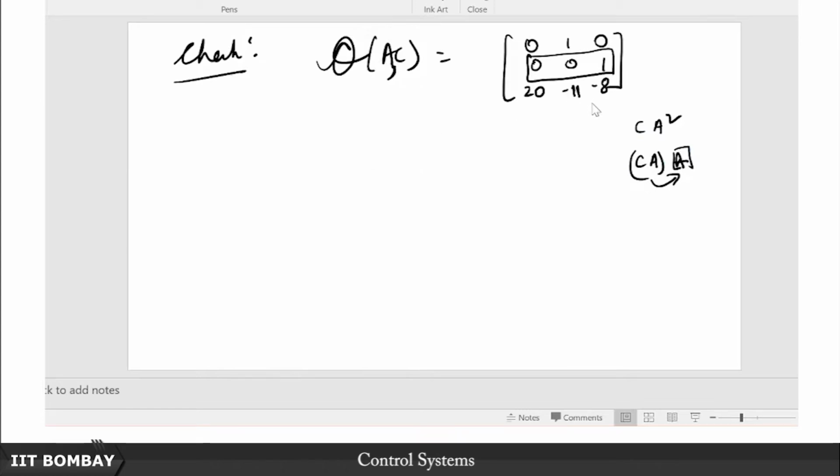This is just incidental, okay, that is what I am trying to say. So in general, do not be misled into the false assumption that the observability matrix obtained from the phase variable canonical form will always be equal to the A matrix. It is not true, it is quite simply not true, it is just true in this particular example in a funny sort of way. And you can clearly now understand what is the rank of this matrix.